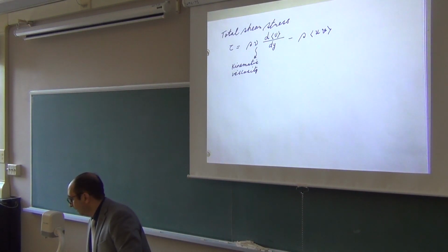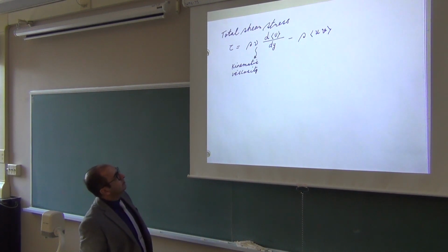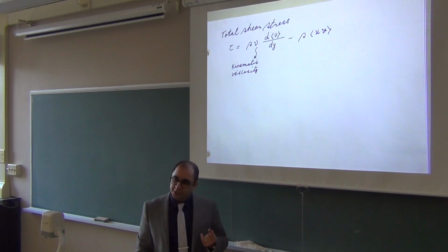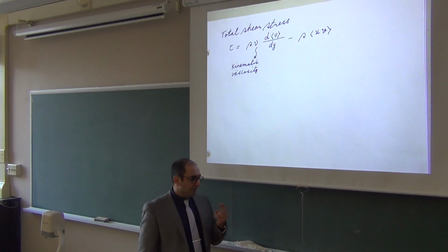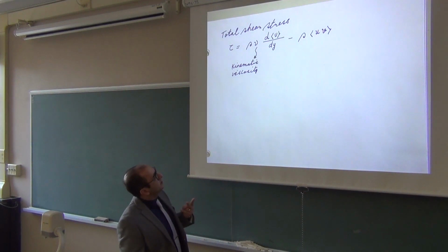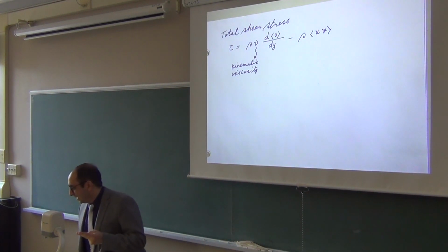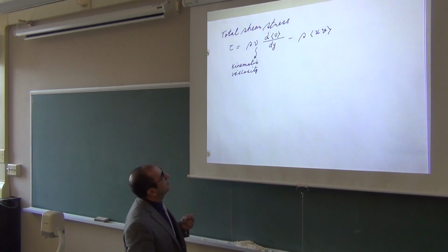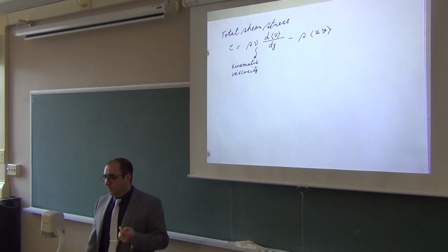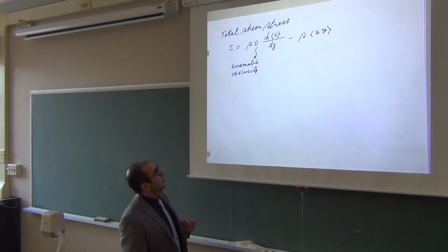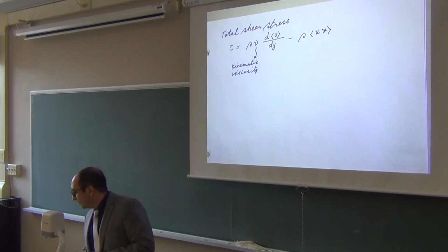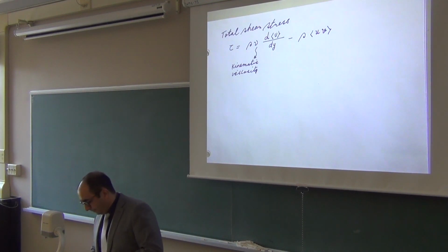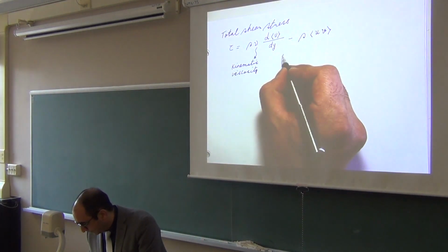And this is telling me something about the components of the shear stress. It means that if you have friction or shear stress in turbulent flow, it's coming from two contributions. The first contribution comes from the viscous or laminar aspect, the viscous side of the flow. Flows have viscosity. Viscosity is some form of friction. It will slow down the flow. That's the first term. And the second term is the turbulent.